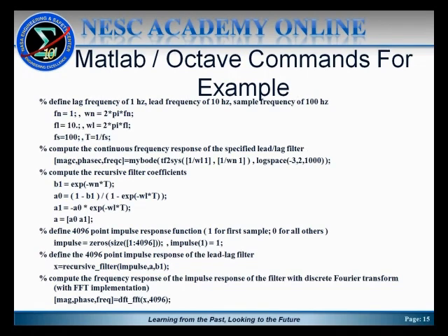And then, after computing it to be filled with zeros, we'll set value number 1 equal to 1. That's what an impulse response function is. It has a value of 1 for the first sample and 0 for all others. Then we'll actually use a recursive filter, which is basically implementing the equations that I showed earlier for how you would condition a filter if you know what the numerator polynomial A is and the denominator coefficients B are.